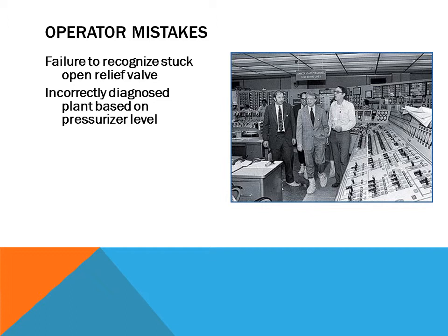But eventually the steam generator did run out of water and caused the heat up and pressurizer level to continue to rise, which again caused the operators to determine they don't need the high pressure injection pumps, even though pressure dropped. So they secured those pumps also.